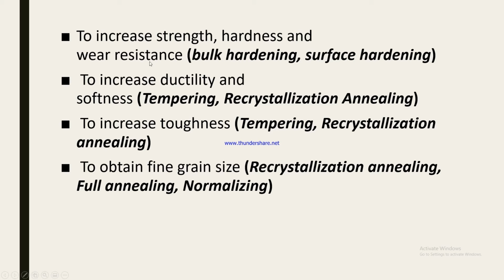To increase ductility and softness, like tempering, recrystallization, annealing. To increase toughness by tempering, recrystallization, annealing, and to obtain fine grain size, same by recrystallization, annealing, full annealing, and normalizing.